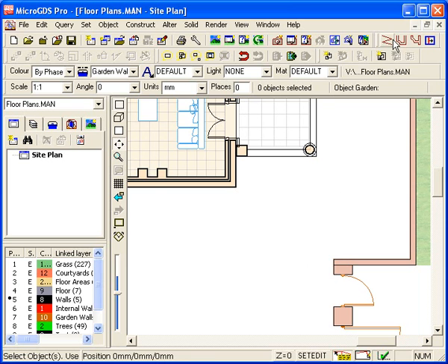I'm going to click onto the Construct Line command and start with a point snap on the wall corner. Move my mouse away from the corner and you will notice immediately I have a dashed construction line across my screen and the angle of the line labelled as minus 180 degrees. If I were to have moved my mouse the other side of my last snap point, which is indicated by this small circle, I have an angle label of 0 degrees.